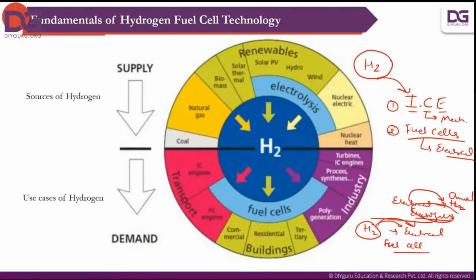The IC engine is the same thing that you have learned in the automobile part, how they work. There is an intake of the fuel in a closed chamber. Then we compress this fuel, then we do the ignition. Ignition is basically the combustion part. After combustion it generates power, and due to this power stroke the piston moves down.